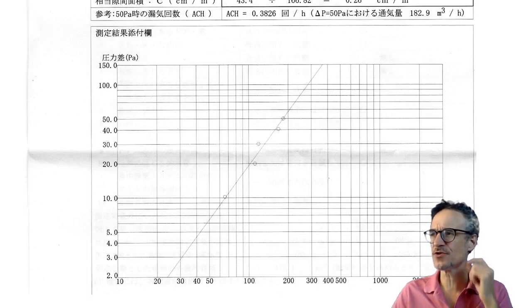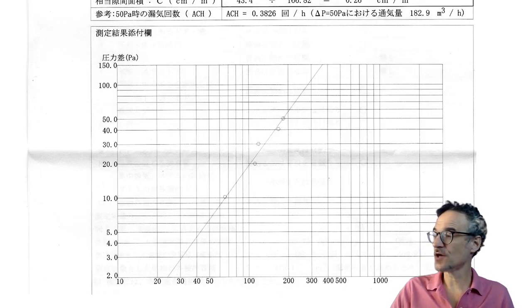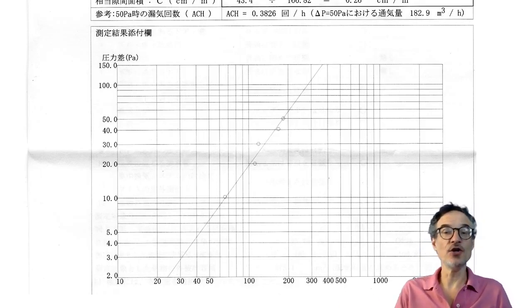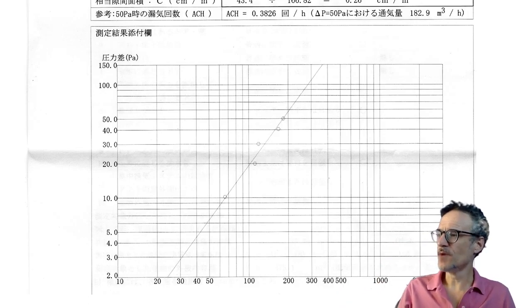So we can measure this, and we do measure this for low energy buildings because air tightness is important. When you measure it, you get a graph something like this. So this is a plot of the pressure and how much air is leaking through. And from this, we can work out how many air changes per hour. And you can also calculate back to the C value from these measurements. So that's how to measure air tightness.